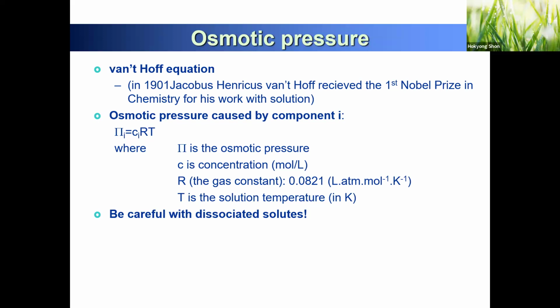So when you calculate your pressure and want to design, with 50% recovery your osmotic pressure goes from 27 bar, and the double concentration of the brine will be 54 bar.